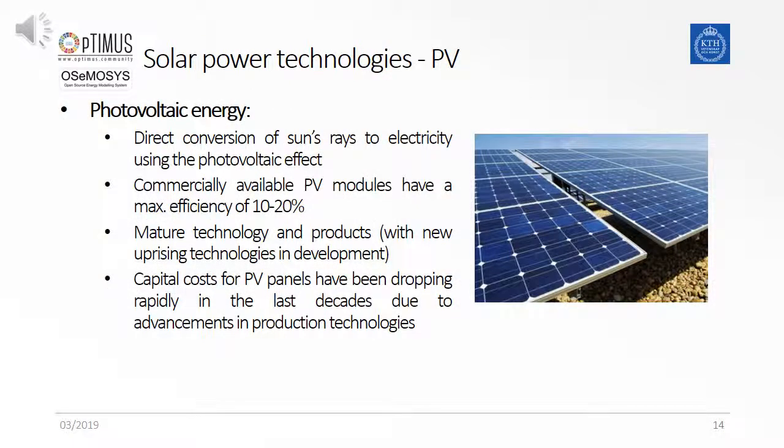PV panels are usually silicon-based crystals utilizing the photovoltaic effect of light photons to generate an electric current. Efficiencies of PV panels can surpass more than 40%, but an average efficiency in most commercial cases is assumed to be around 15%. This value is rarely reached per year in northern regions. PV panels can be considered a very mature technology, and there are many products available on the market.